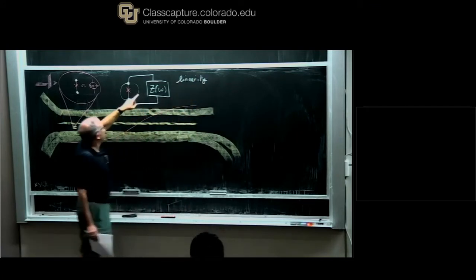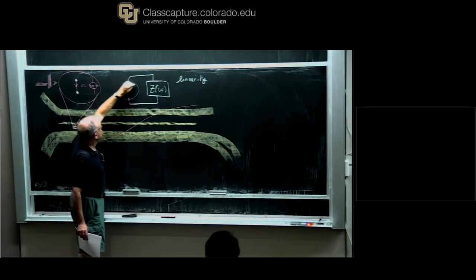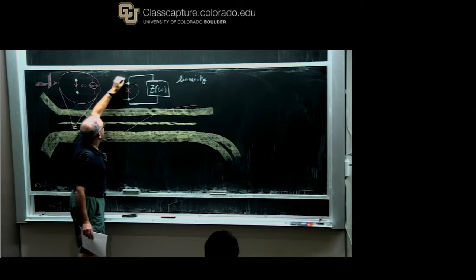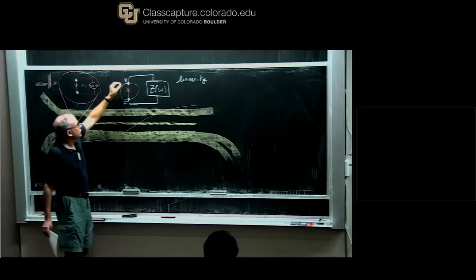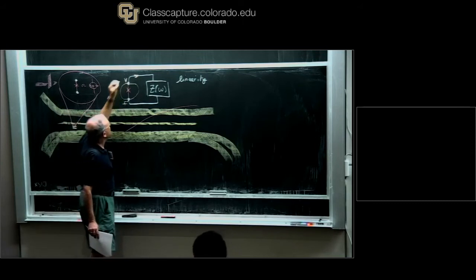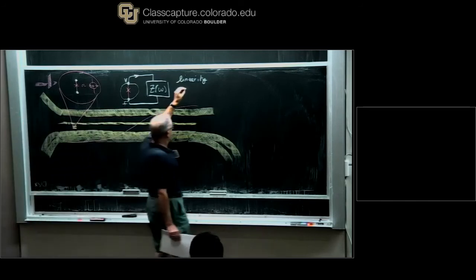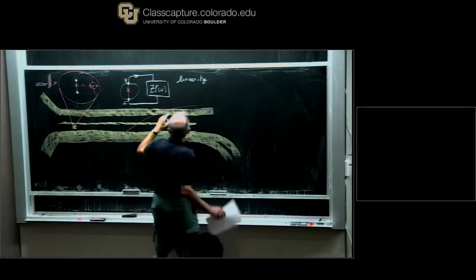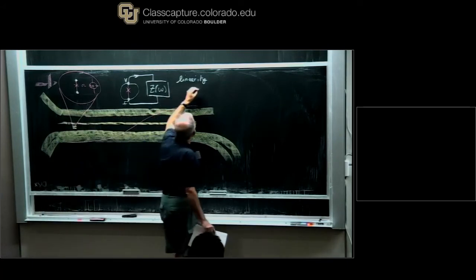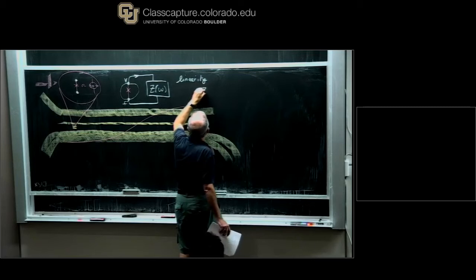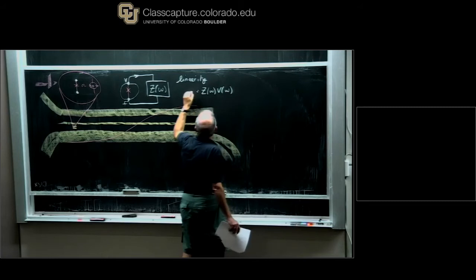And then, what we mean by the linear response, we have only 2 quantities. Classically, we have the voltage. We can put a ground here for the moment, but there's a voltage here, and that causes there to be a current, a linear response current. So the meaning of this, you might say Green's function, this sort of discrete Green's function, is that Z of omega times V of omega is I of omega.